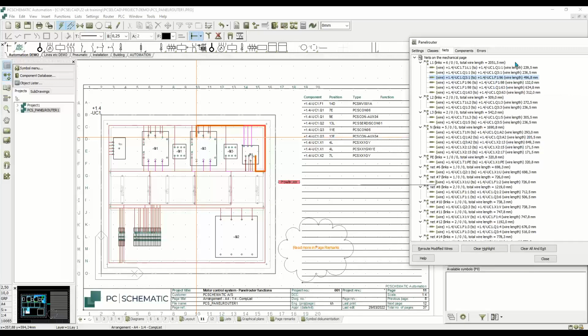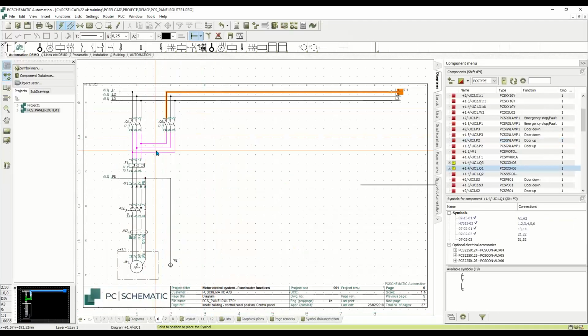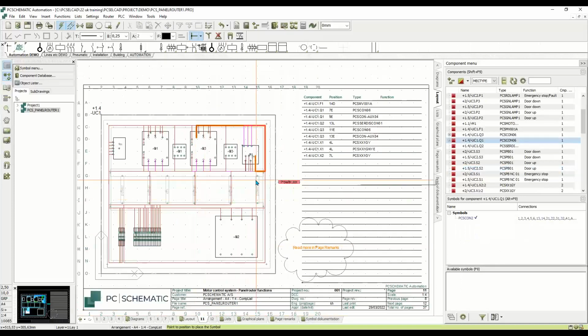But we also might have, and I'll just close this one here, if I look here, I have this wire here and this and this. Those two wires, three lines, also have the same potential, and that's also a net. So when we go in and look at nets, we base it on the schematics. So that's what we can see here.